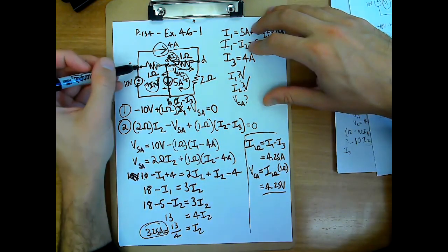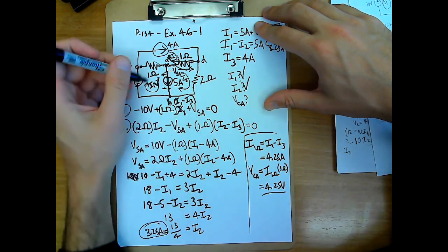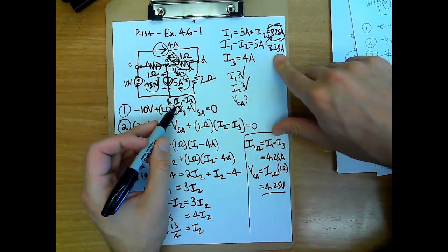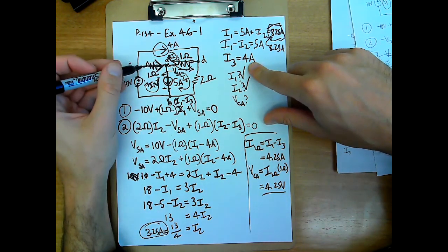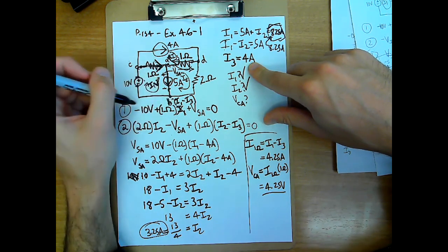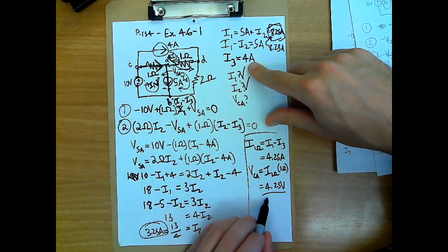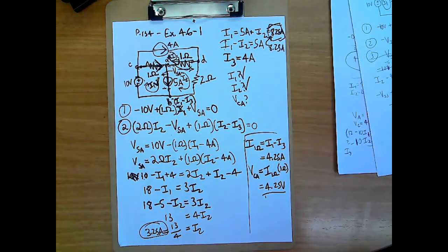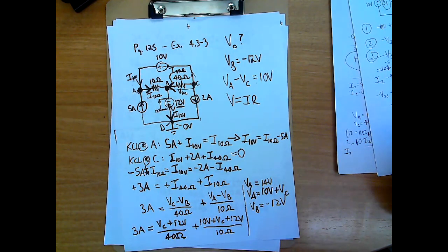And I know that it's higher here than here because, again, I said if I1 is greater than I3, the voltage drop would be in the direction of the mesh current. Well, I1 is 8.25. Subtract 4 off of that means the actual current's going in that direction, consistent with what my sign convention was when I made these mesh equations. So I know that this is the voltage drop from C to A. It's higher at C than it is at A. All right, so that's mesh equations. It's node equations. Talk about them a little bit more, but if you have any questions, feel free to reference this and feel free to ask.